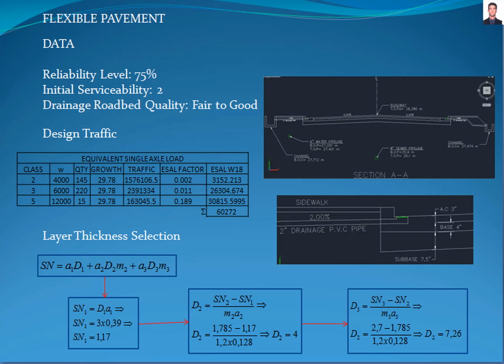In this tutorial, we're going to design the flexible pavement structure for the urbanism. The roads of an urbanism are considered low-volume traffic road structures because they aren't expected to convey a significant level of truck traffic. The urbanism is on filled ground with a CBR of 10%, which represents the roadbed. The design is based on section 4.2.1 of the AASHTO guide for design of pavement structures for low traffic